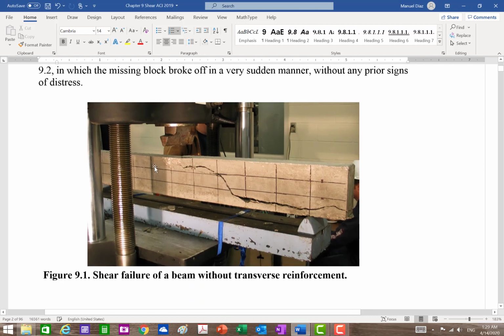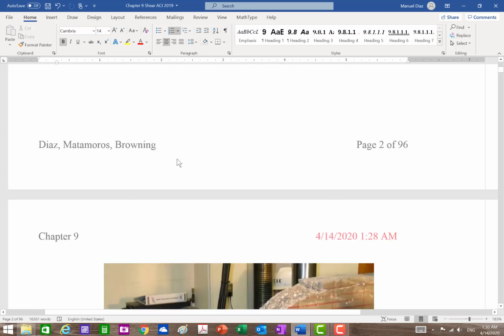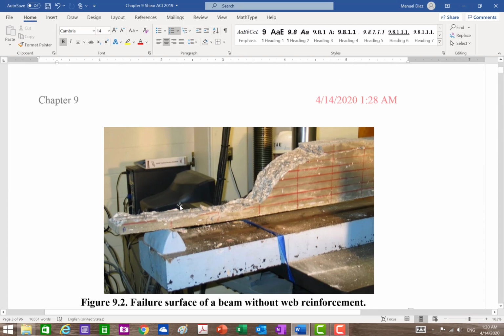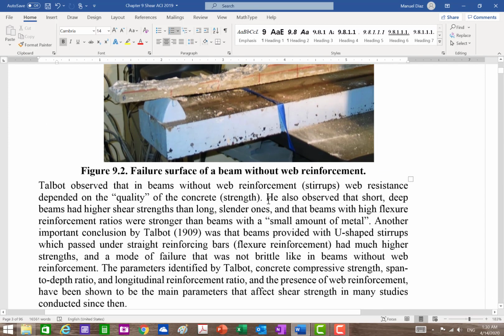Okay, here is just a typical shear failure. It normally starts at some point here, the neutral axis. I think it propagates around the tension side, and it usually follows the line of the rebars and separates from it, right? And we call it debonding. Or it can go up and then cause spalling because it's a compression failure, right? So you remove that section, and this is kind of what you get.